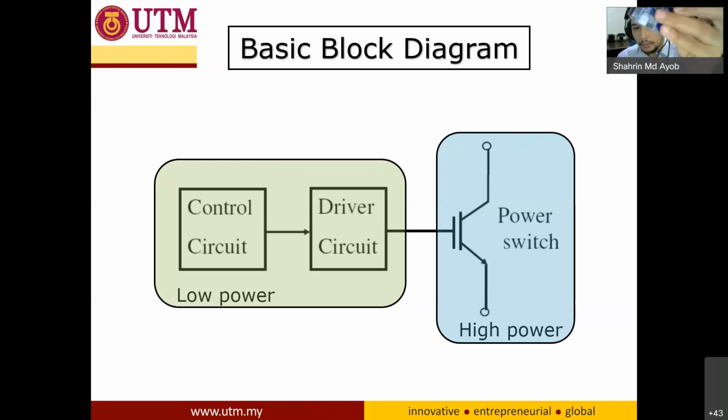Right now, the output signal from the Uno is 5 volt. So how to turn on the MOSFET? The MOSFET requires 15 volt. To turn it on, the control signal must be 15 volt. But right now, the output from the Arduino Uno is 5 volt.